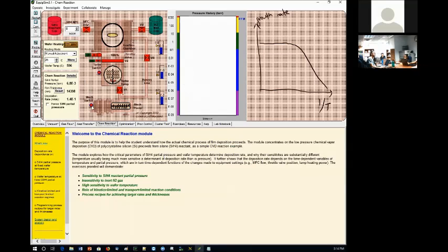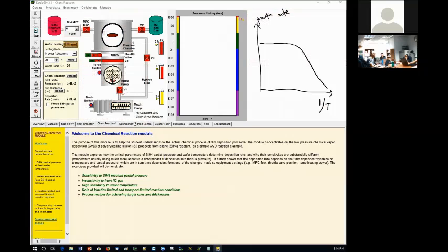Okay, so let's do it together, starting the simulation tool, turning on the mechanical pump, turning on this valve, turning on turbo, because I don't care at this point. You guys are familiar with everything, so it's all nice. You can set this to 100 because we're not going to set it to something else. So 100 SCCM silane is coming from the mass flow controller. I open that up too. The throttle valve is, I guess, open. Yeah, 100% open.